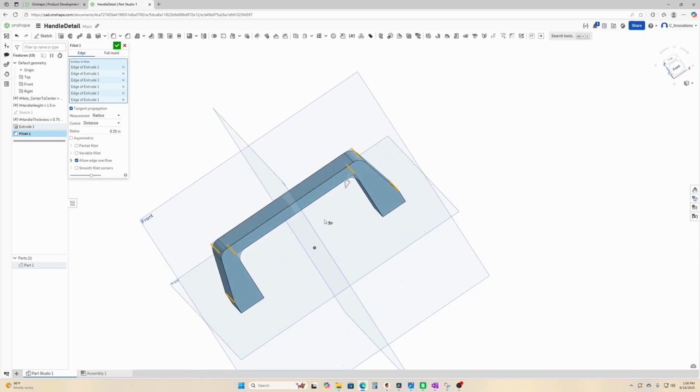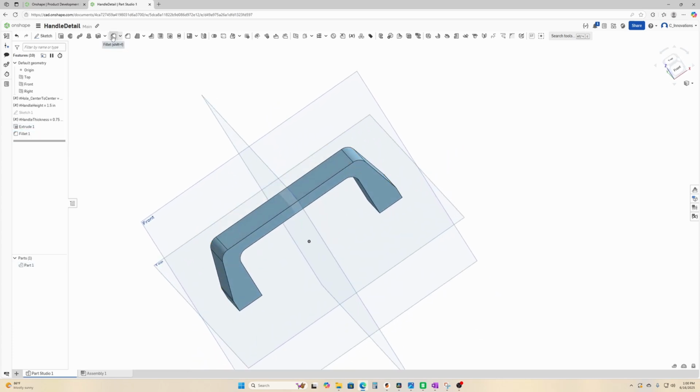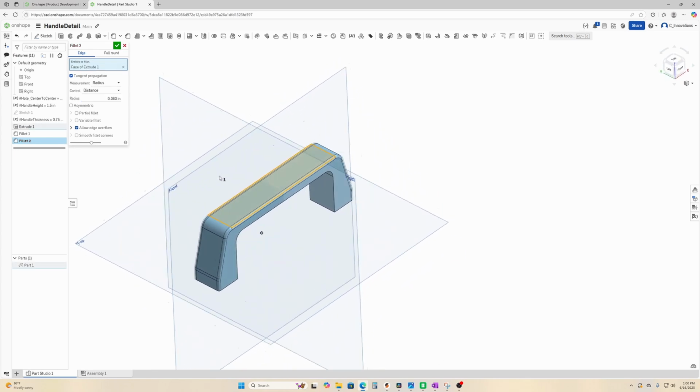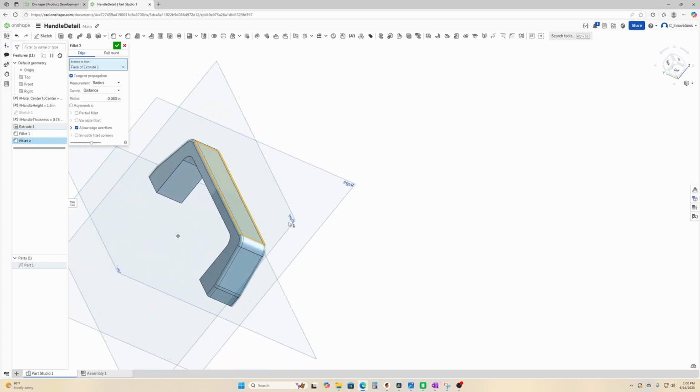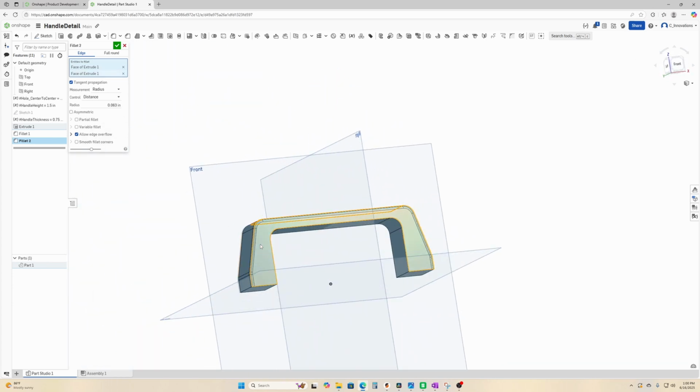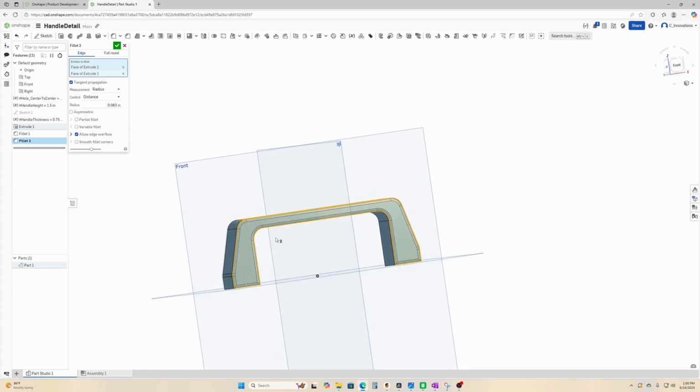Under there. We'll add some more fillets. A much smaller one called a 1/16 of an inch. And one thing you can do is you can just select that face and it'll do all the edges there, which is pretty nice. I don't want that because I don't want that fillet necessarily on the bottom.